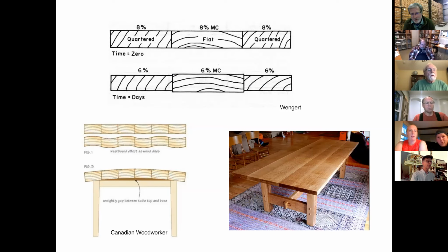And you can notice this if you go to a lot of restaurants that don't necessarily have the highest quality solid wood materials. If you look at the light shining on the tables at most restaurants, you can see these changes occur in the piece of wood. It's kind of interesting. You can see the shadow effect with the light on there. Another thing you have to avoid in really wide tabletops is using the same plane of reference, the same direction, throughout the width of the piece.